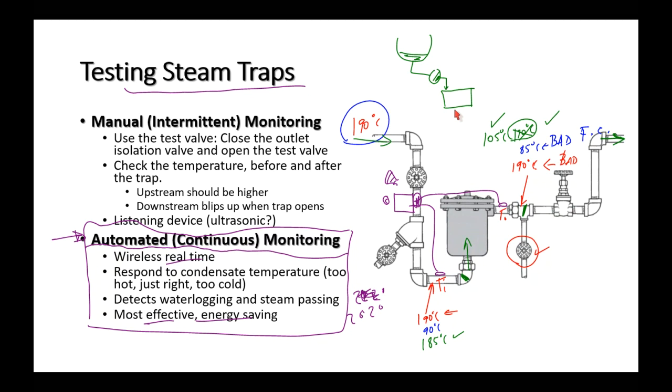Because we put steam onto the mud drums to keep the boiler warm during its non-operational period. But anyway, so the condensate will accumulate in a tank, and the tank will have a float, and that float will operate a pump. And the pump then will start and stop according to the level inside the condensate tank. And then it could go in a few different places. So depends upon the plant, but you might have, say, a very large condensate receiver.